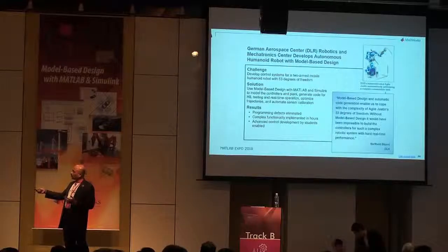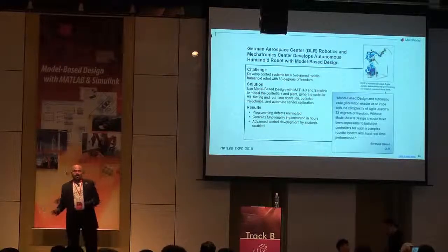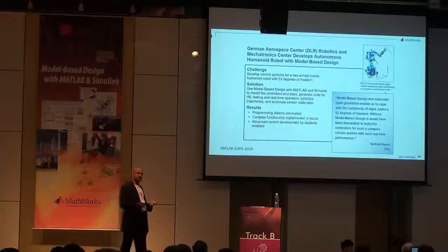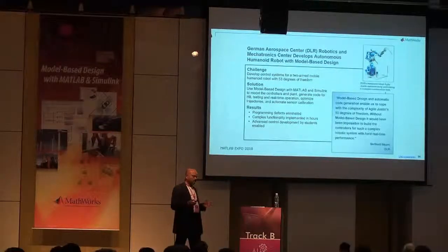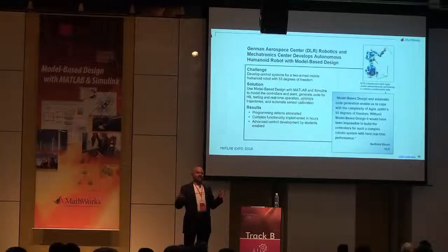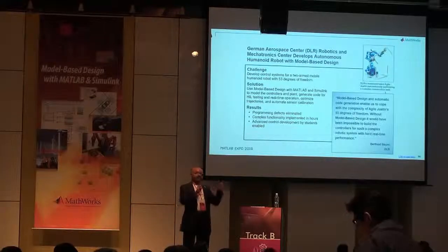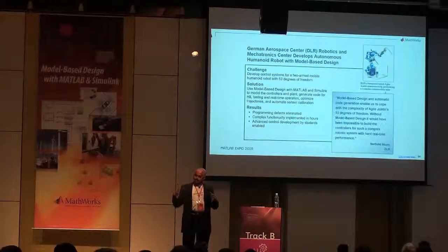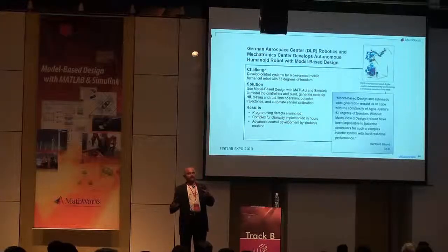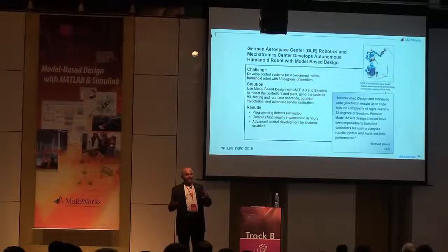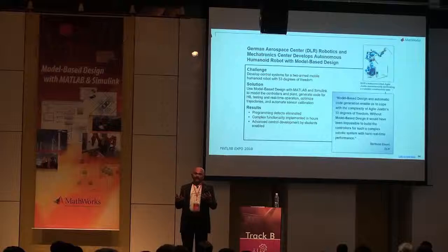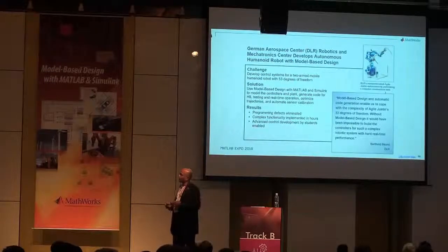You'll see this thing here called HIL testing. All HIL testing is all about is hardware-in-the-loop testing, where how do you do testing when the real robot is not built yet? So instead of waiting for the real robot to be built, what you do is use a simulation model of the robot, run that on a real-time PC, and then connect your controller to it. The controller thinks it's controlling the real robot, but instead it's controlling the real-time simulation of the robot. And by doing that, you can get a complete verification of how your system performs.